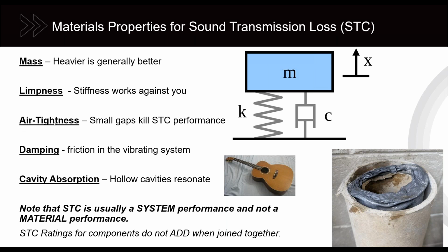Further, air tightness: small gaps will kill your STC performance much more than you might think. And a good example I give of this is, you're in your car, driving on the highway. If you open your window all the way open, you hear all the air turbulence noise and tire noise and everyone's engine and everything just coming clear through the window, right?